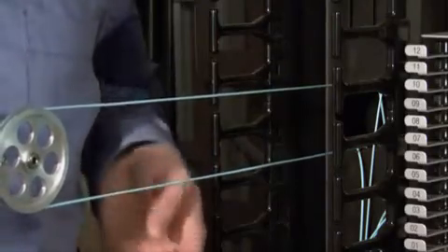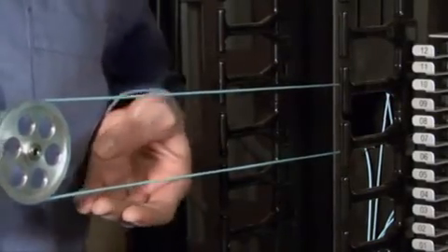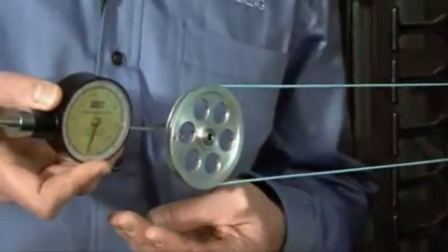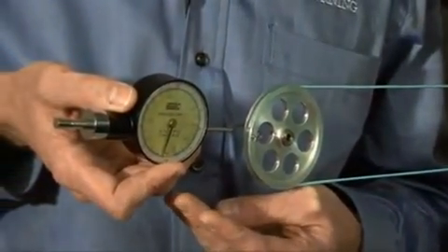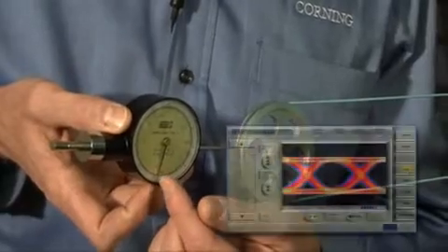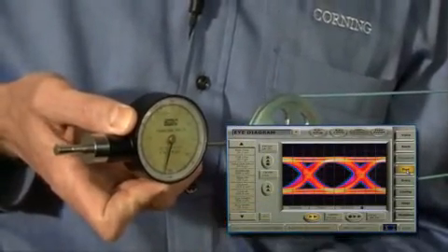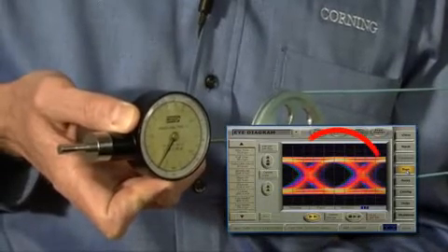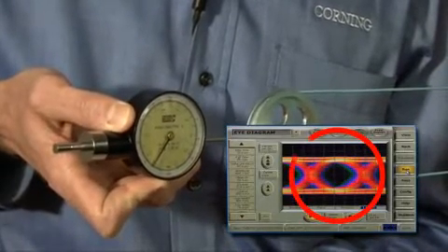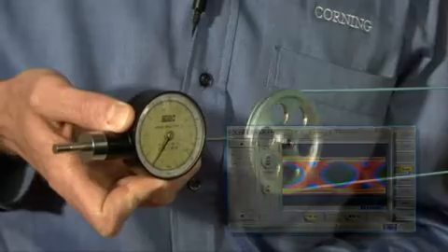This first jumper is a standard multimode. We've attached a load cell so that we can see how much force we're pulling on this jumper with. The gauge goes from 1 pound up to 10 pounds. As we increase the load up to about 1.5 pounds, the error rate rises dramatically, enough to crash the system.